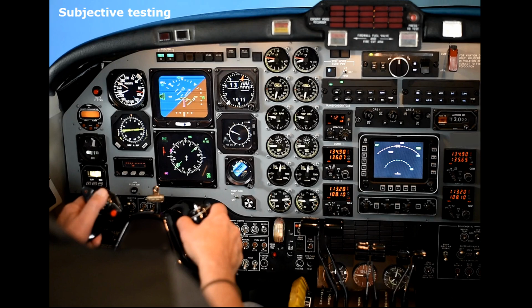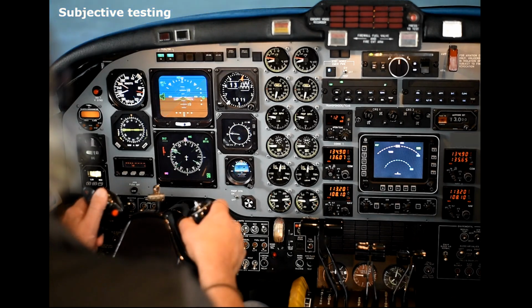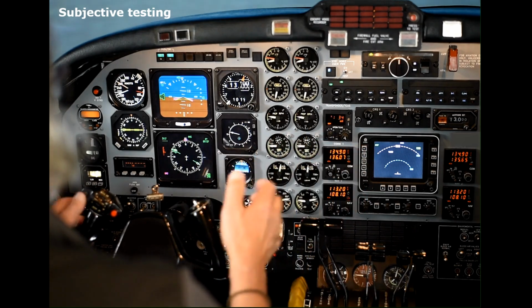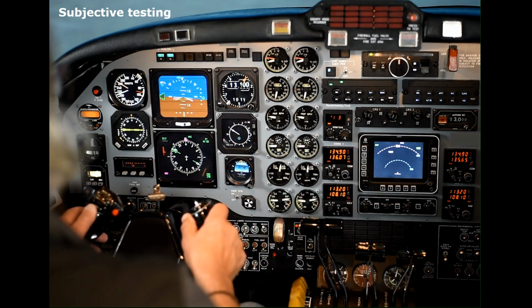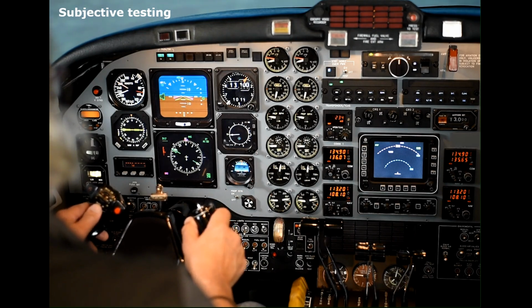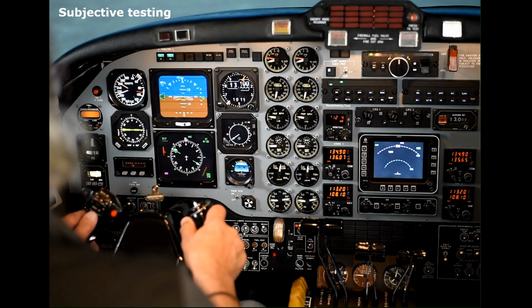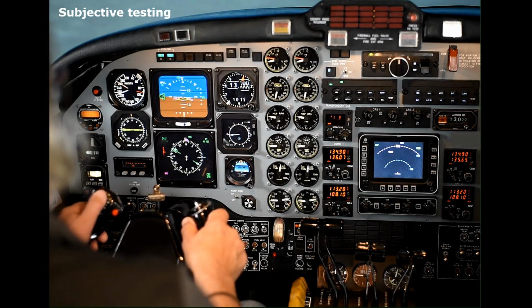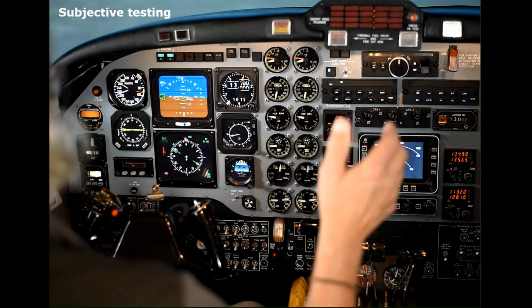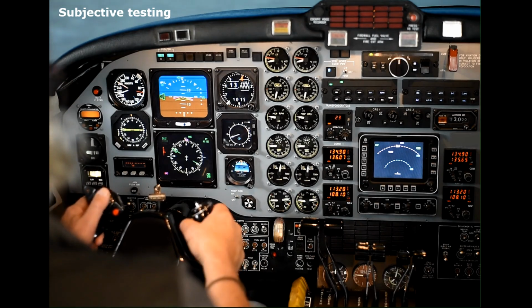An expert pilot is performing subjective testing on some manual handling. Aircraft is flying at about 13,000 feet. We are going to do a steep turns exercise. Autopilot is now disconnected. I take my hands off. As you see, we need a little bit of nose down trim to keep 13,000 feet, to keep it steady. There we go. Release my hands, it's in trim. I'm going to start banking to the right.